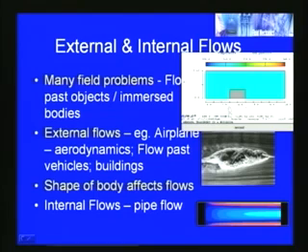Also, here you can see in this typical case, whenever the flow is taking place over the block, the fluid flow will be coming like this, and this solid is not moving. So there is a no slip condition here and a boundary layer is created. Like this, in most external flow problems, there is always a boundary layer created, and we have to deal with this boundary layer.